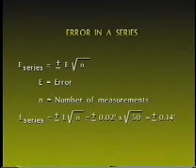Suppose that when a party chief and his chainmen use a 100-foot tape, there is a plus or minus 0.02 foot error from all the error sources. What would be the error if this team had to measure a 5,000-foot distance? In this case, the number of tape lengths in this 5,000-foot distance is 50, and the error of this series would be equal to plus or minus the error, which is 0.02 feet, times the square root of the number of measurements, which is 50. The answer would be plus or minus 0.14 feet.